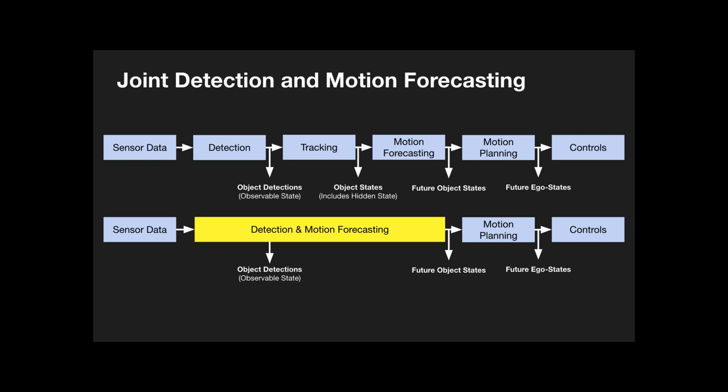So if, for 2 or 3 frames, you see that the output of this is inconsistent with what you're actually seeing, the detections continue to go in a different direction from where the network thought they would be going, then you could set up another system that either tries a more engineered way of tracking this, or we can call it paranoid, that tries to see, okay, I need to slow down, pay more attention to this. I don't know what's going on, but consistently this model is giving wrong estimates.